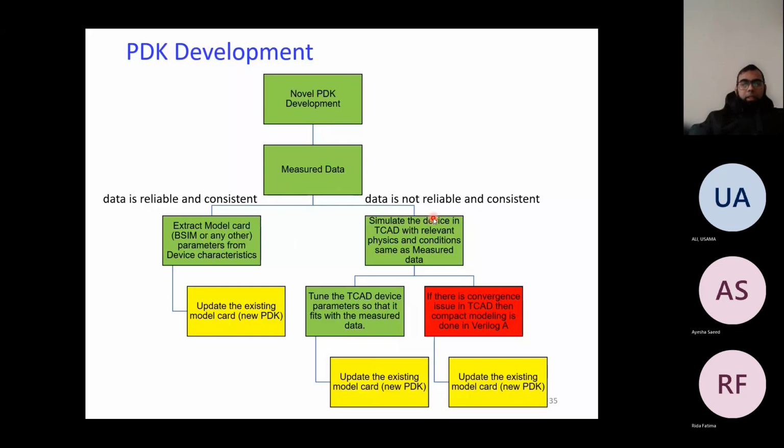It's a numerical simulation. You can Google it, or some of you might be aware of this. Then you understand the physics of the device, and you generate the IV curve from TCAD. Circuit people do circuit simulation; TCAD is basically device simulation. In TCAD you can do everything the foundry is doing, in software. Starting from the process, you fabricate the device in TCAD, then you characterize the device, meaning you apply bias and study the device physics.